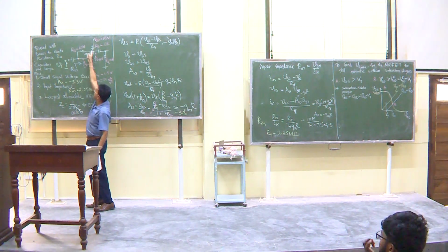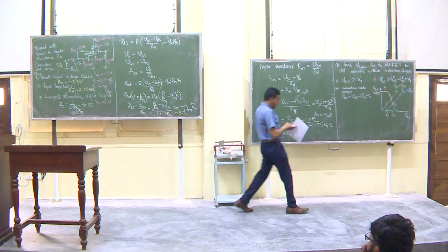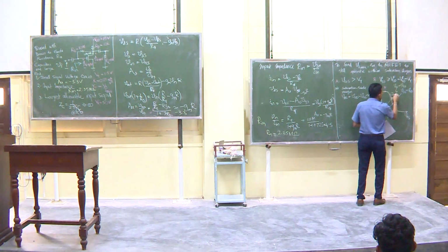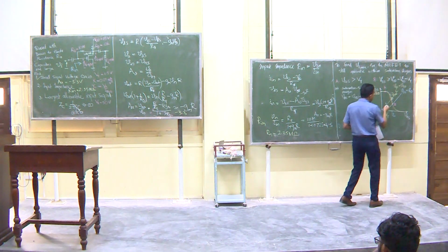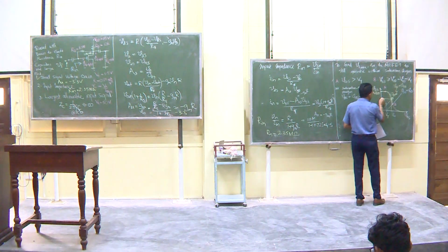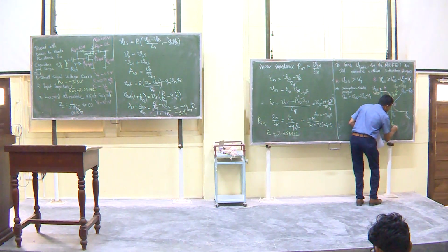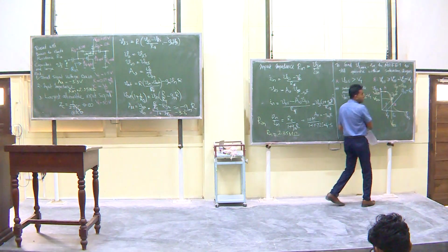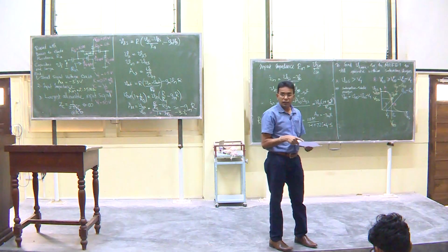Therefore, this voltage is equal to this voltage, VDS equal to VGS. So that has to be my operating point, the Q point. I can mark the points here. This value is VGS capital, this value is VDS capital.